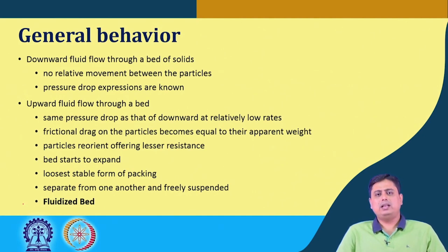Once there is no contact between the particles, we say that the bed is now fluidized. So just before that, at the onset of fluidization, we will have the loosest possible stable form of the packing, which will have the maximum porosity or voidage of the bed.